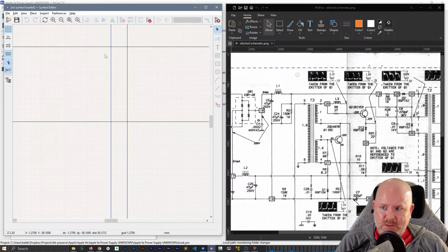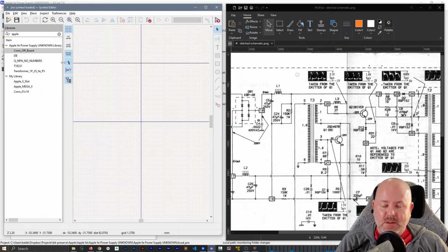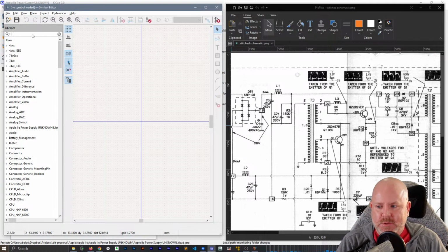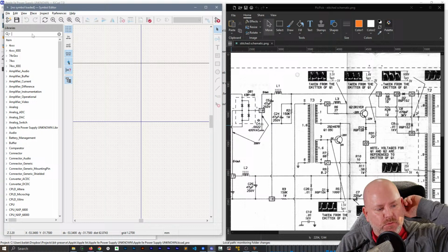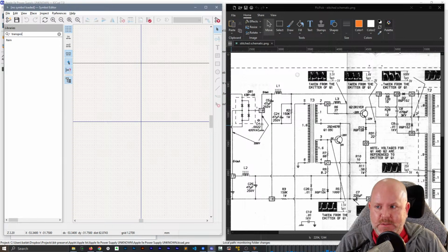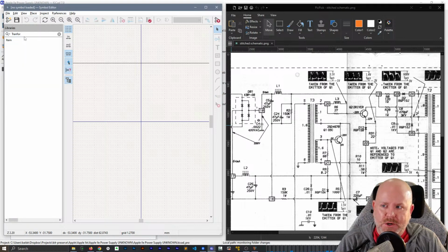For example, the simulator in KiCad is not what I would even remotely consider usable unless you're very familiar with PSpice. It's not like the Falstad simulator where you can drag and drop parts and it updates in real time, and it gives you real time numbers. It is really meant to be an analysis tool. And it's really hard to do an analysis if you don't know what you're analyzing.